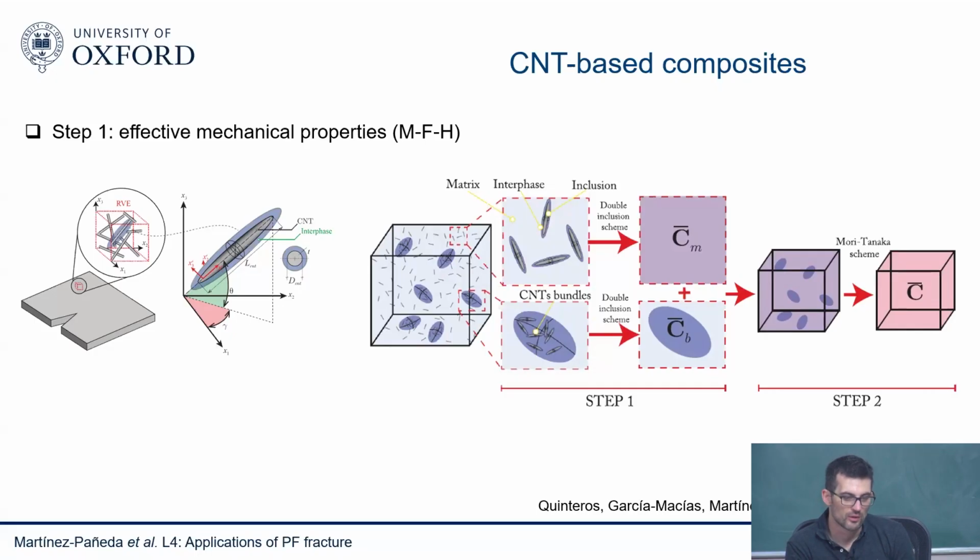So the idea is to either embed those carbon nanotubes into concrete or create some composites that will act as some sort of smart skins. So there's an idea of monitoring structures for damage. This is often complicated and done at a global level, but often a lot of the problems that we have in structures are local, like corrosion and so on. So we want to put those skins somewhere where they tell us some sort of local damage has occurred.